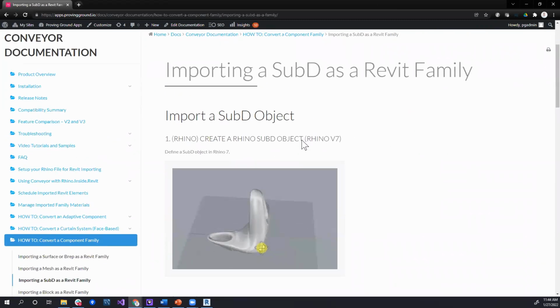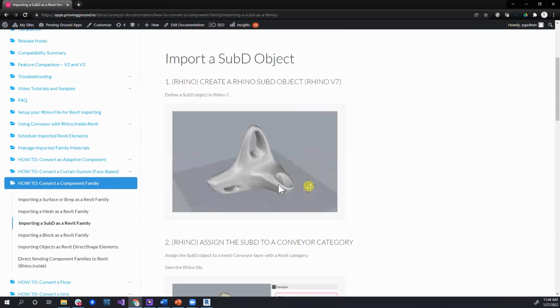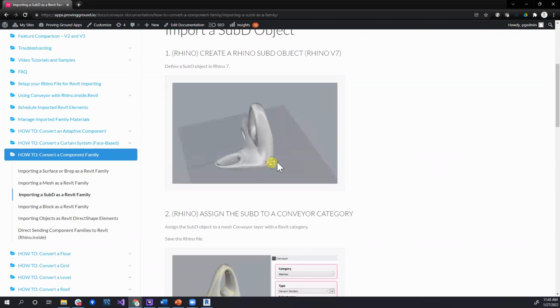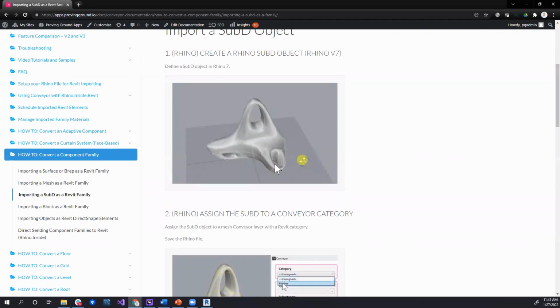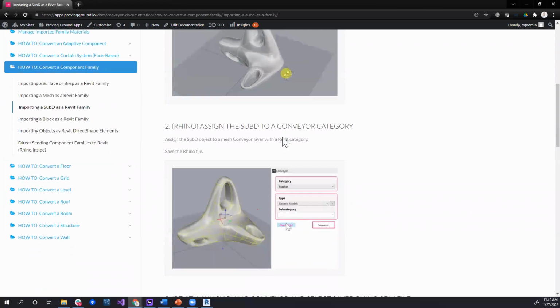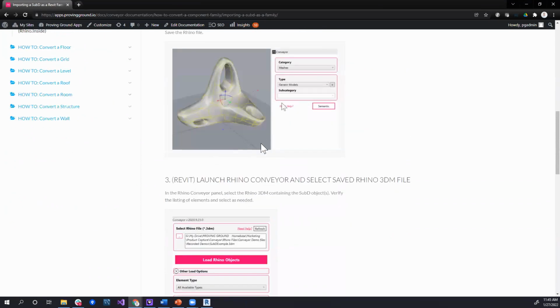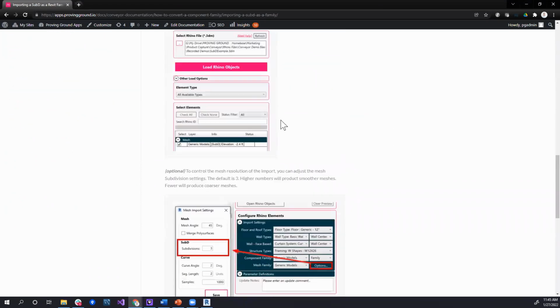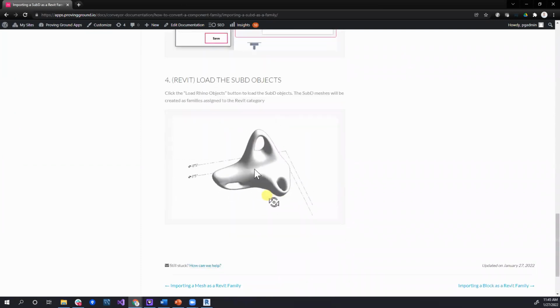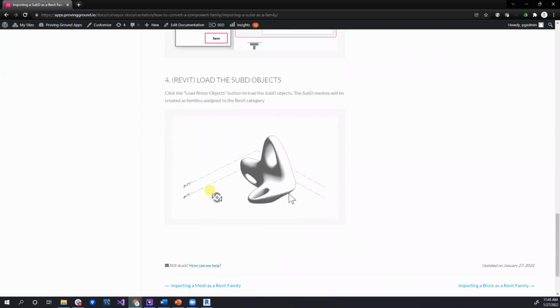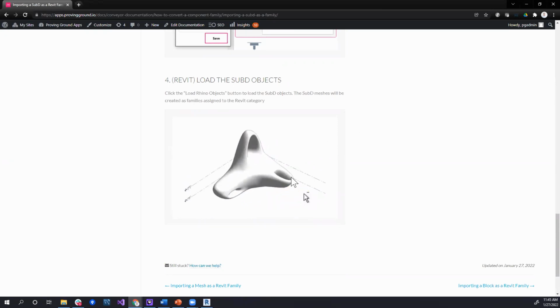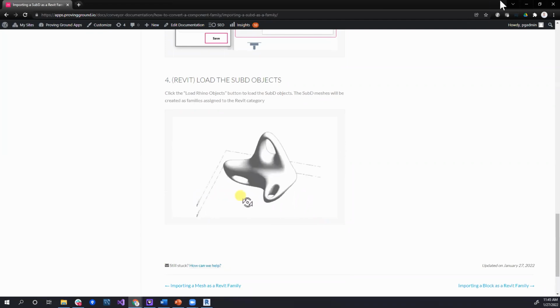I like the sub-D one because there's some cool geometry there to work with, and that's something that's conventionally really hard to bring into the Revit environment in a way where these objects can be well situated from a documentation perspective. So our sub-D objects, this is a complete aside, use mesh-based conversion and some of our novel mesh processing that allows for you to have hidden edge meshes in the Revit document. So you end up with these very clean hidden edge representations of mesh objects.